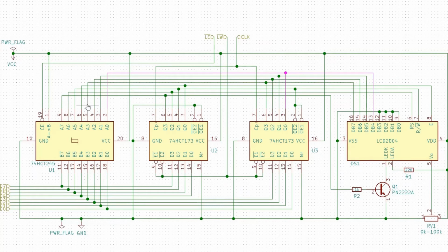And this bus transceiver is active as soon as that LE control line is held low, and thus displays the data from the display and the data from the control register to the data bus, which is shown here on the left hand side.